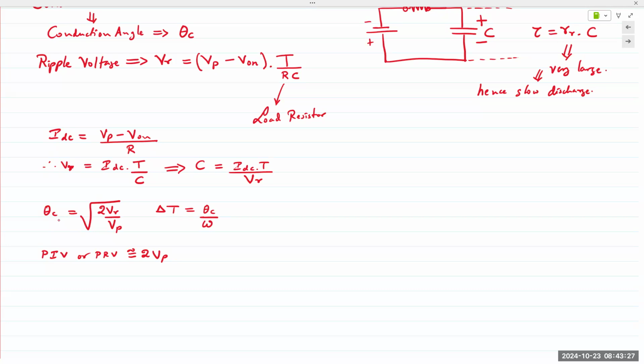So we apply a capacitor, but for a full wave rectifier, now we have 2 peaks. So twice as much frequency. If it's a 60 hertz signal input, half wave will still have 60 hertz at the output, but a full wave will be twice as much, so 120 hertz. So most of the equations are still the same, except there are some places where we double everything. The first place where we double it would be the diode turn-on voltage.